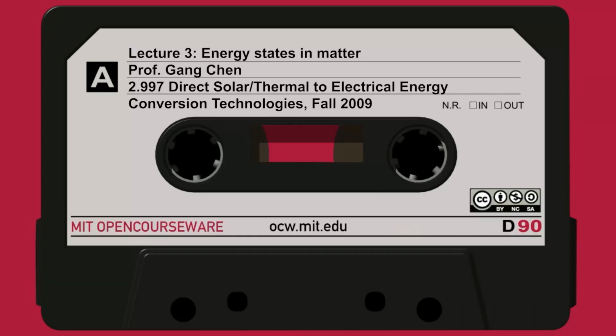Okay, there's a big difference in these two materials, direct and indirect. The microelectronics industry is established on silicon, but for the lasers, semiconductor lasers, nobody can use silicon to make semiconductor lasers. People are making progress, but it's much more difficult to make a laser out of silicon. It's much easier with a direct gap semiconductor.